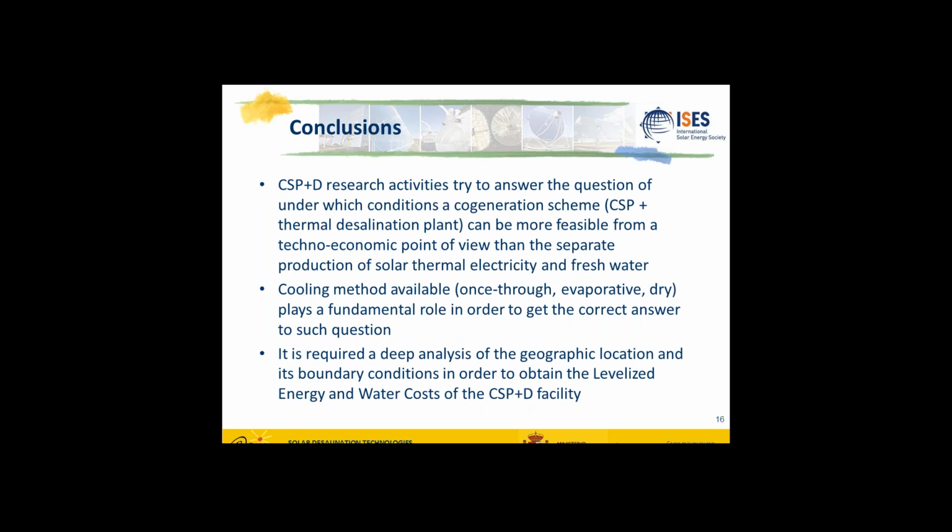In this case, we still conserve the final condenser, so we can make the power production process independent from the fresh water production process. Okay. In this case, we are also taking advantage that we don't need to condense as much, so the size of the condenser could be a little bit smaller.